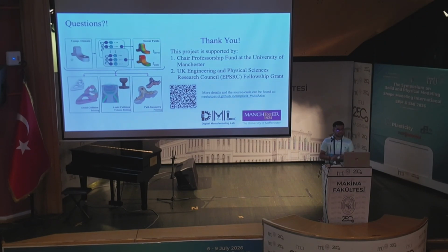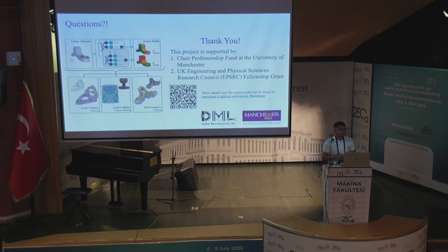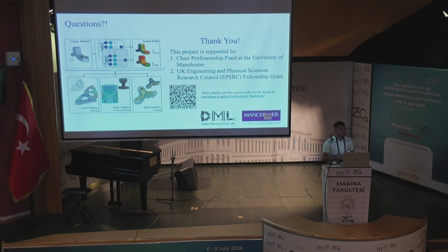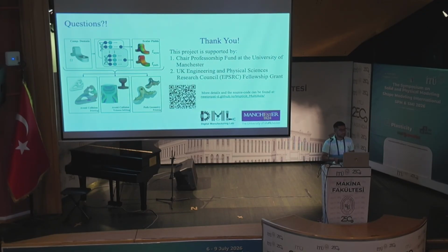There are multiple reasons. First is that the conventional printers print at a very low layer height, and because we wanted to test our parts and had less time, we increased the layer height several times. Let's say the Bamboo printers print at 0.2 millimeter height, we print at 0.6 millimeter height.